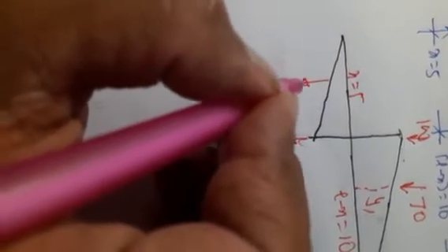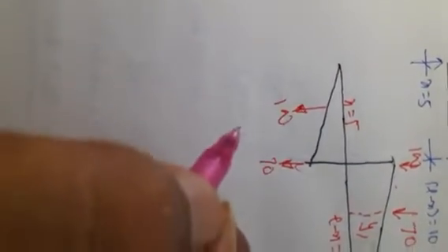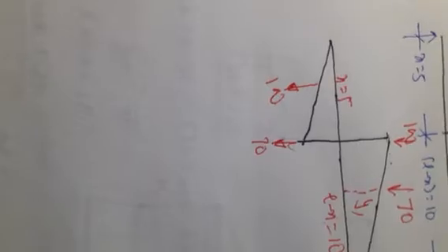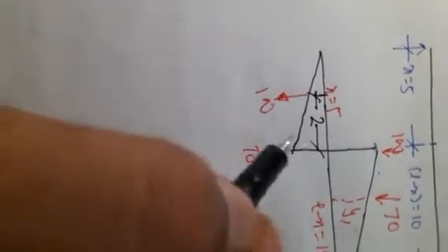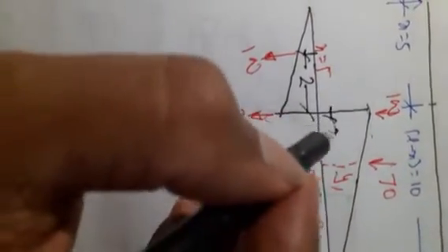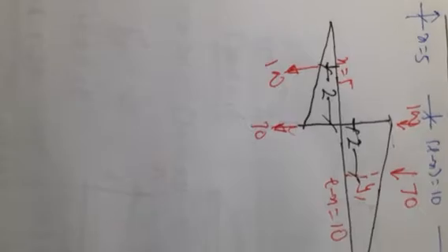Let this ordinate be y1. Second, the loads are to the left. So the 70 front load is here, the 100 kilonewton load is here. Now mark the distances. This distance from here till here is 2. This distance is 2.